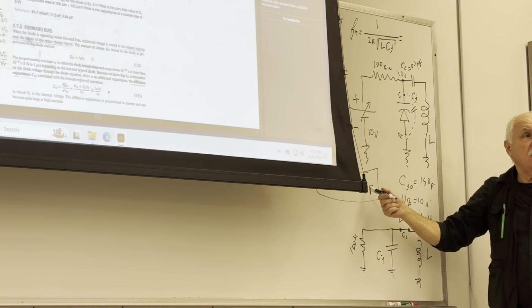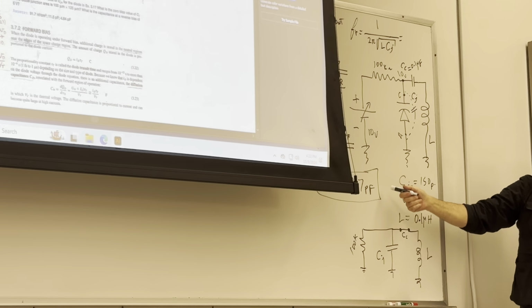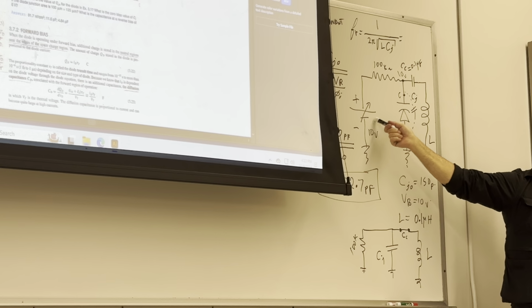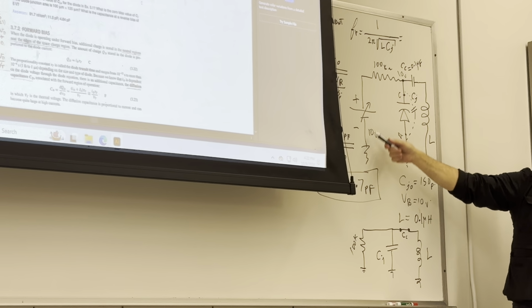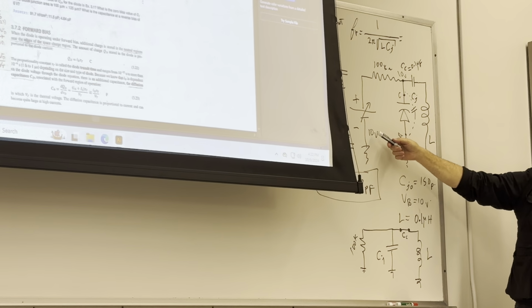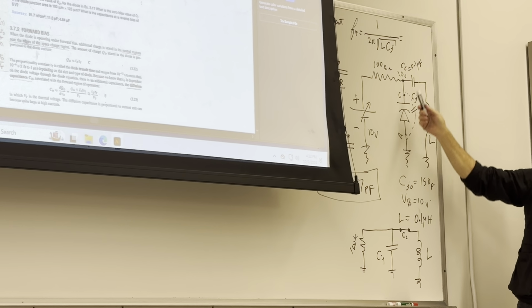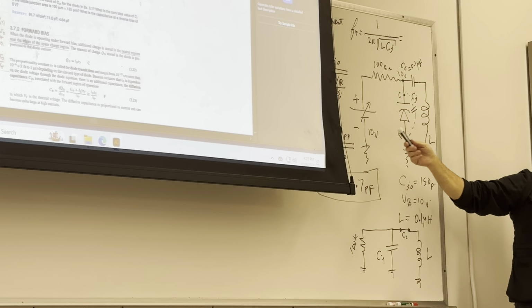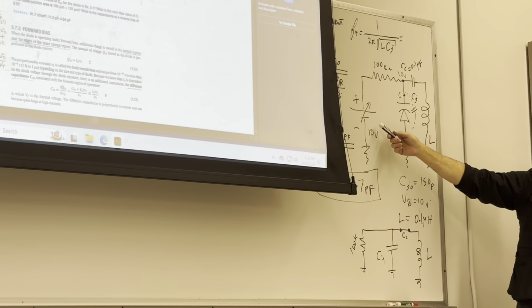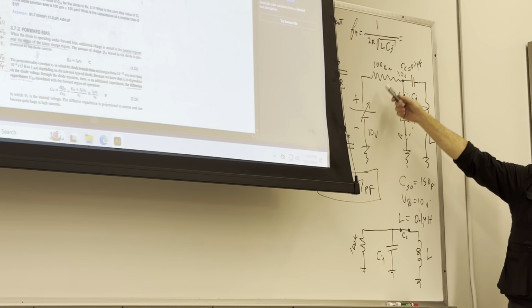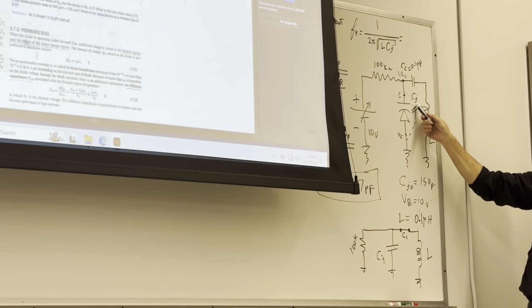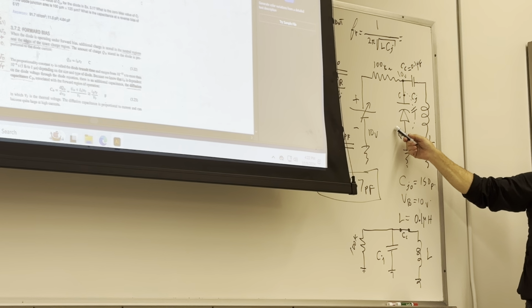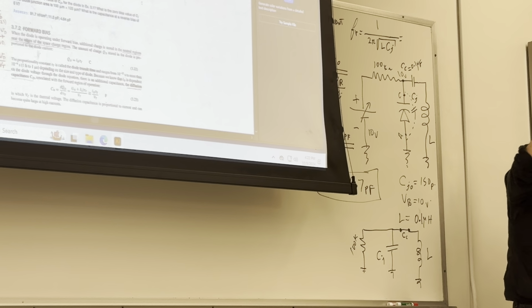Can we change that capacitance value? Can we alter that? Yes. That's the key. Keep changing this voltage. Take it to a very, very large level, and it will get very, very small. But remember one thing, how high you can go. You put large voltage there, this diode goes to reverse, right? Do you remember what happened to the diodes in the reverse region?